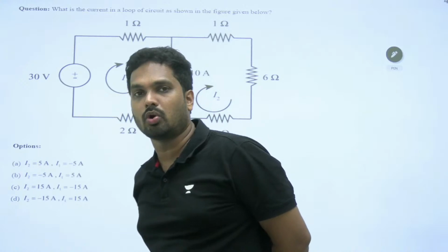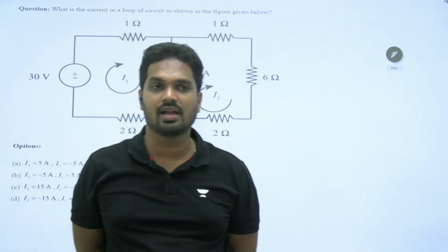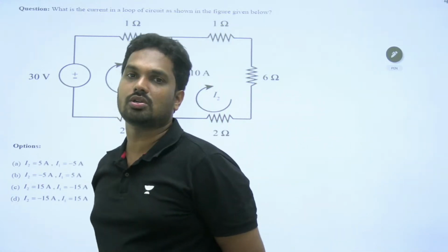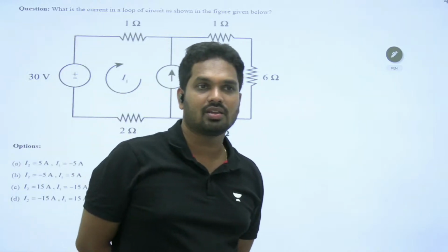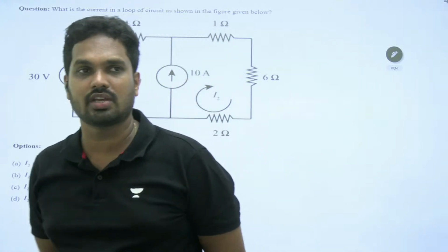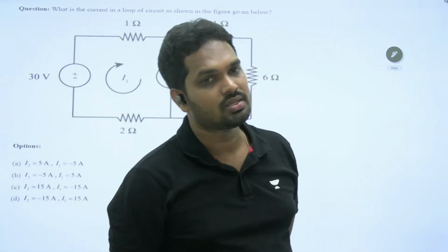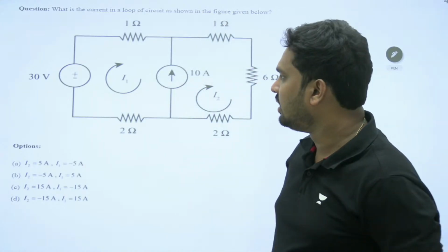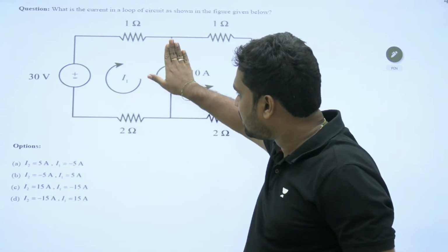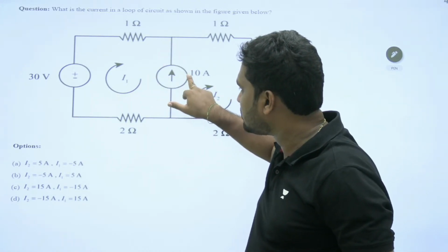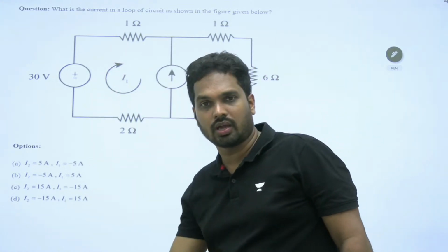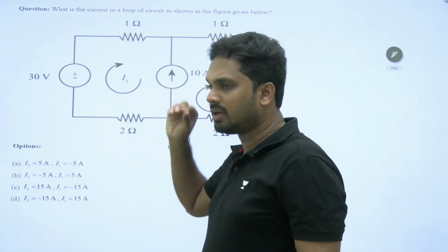Because here two important points generally we will be discussing in the regular class, the basics में, voltage source का current is an unknown quantity, current source का voltage is an unknown quantity. Whenever they come in our network, if you need to find the current in the voltage source or voltage across the current source, उस case में we should avoid it or do it by some alternative method. Here if you write the loop equation in this direction, क्या दिक्कत मिलते हैं आपको? You need to write the voltage across it, which is impossible because you cannot find the voltage of the current source. It depends on the remaining network. Okay, so this is the condition of super mesh example.